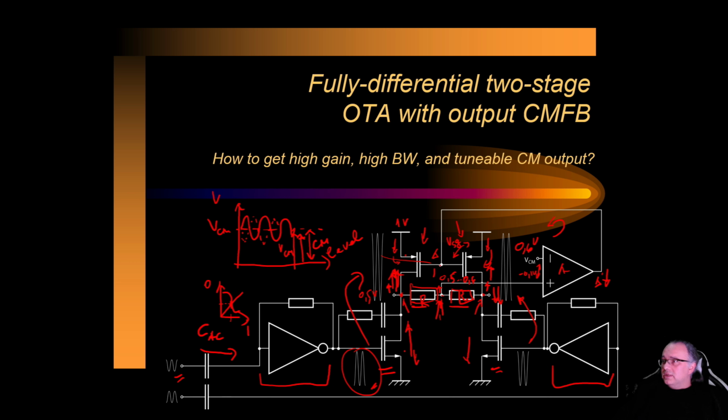and then this node will set the proper source gate voltage of the pmos transistor, so that this node here in the middle is 0.6 volts, which means that then the common mode of the output signal will be 0.6 volts. At a certain moment, if we want to go to 0.5 volt, the mechanism repeats and the output voltage sets to the desired level. In this way, we can set the common mode of the signal, and we can move it upwards or downwards to the respective level that we want.